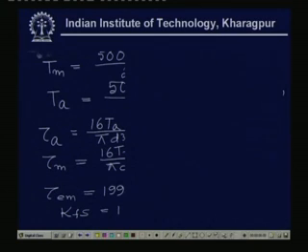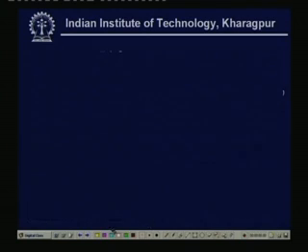as we have discussed, so that the equation can be written in this way: tau equivalent, you remember it will be tau yield point divided by factor of safety yield point. If I use a Soderberg criterion, then this comes out to be like that.